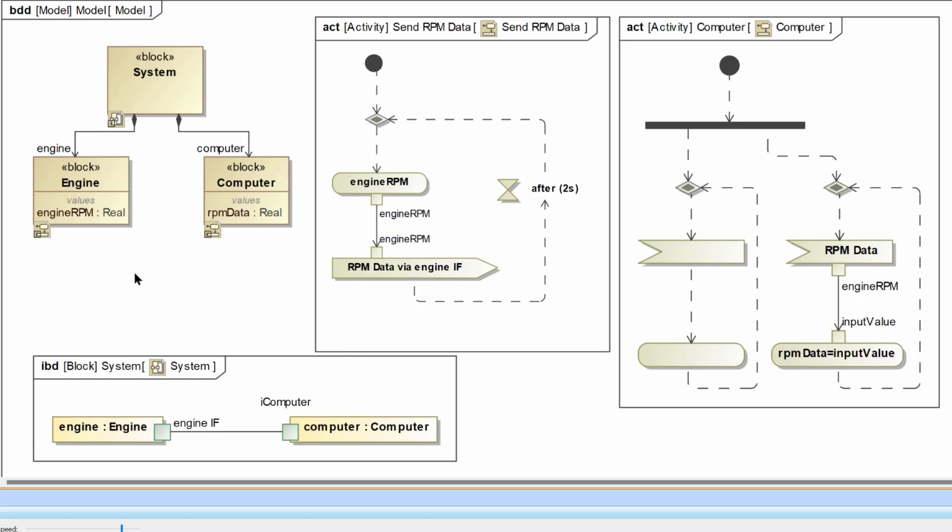But keep in mind, states are really there to encapsulate behaviors at specific times and inhibit those behaviors at other times. So that's what state machines are good for, is actually inhibiting certain behaviors from happening unless that part of your system is in a specific state. And a lot of times those states end up having a name, and then they simply call these other behaviors. So a lot of times you'll end up right back at where you started with activity diagrams, but state machines can be really useful for that as well.